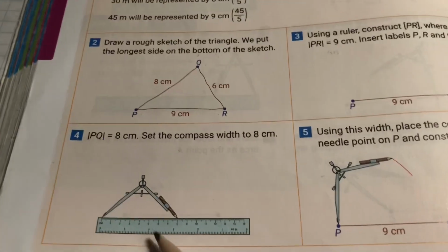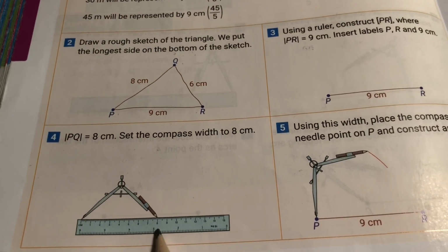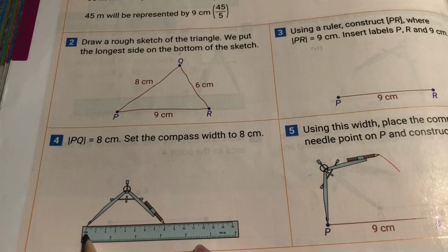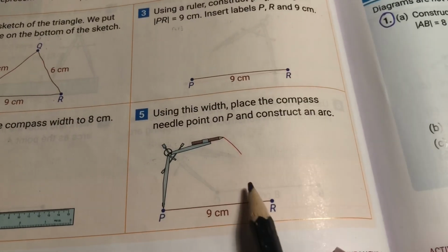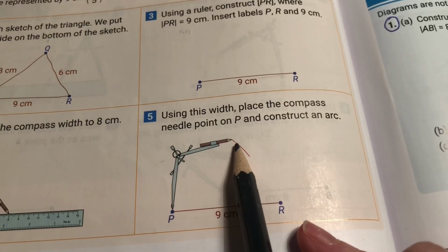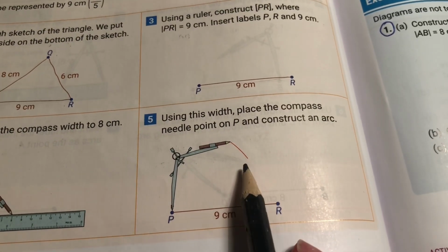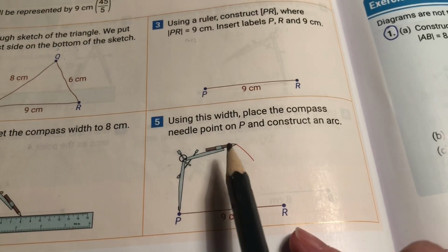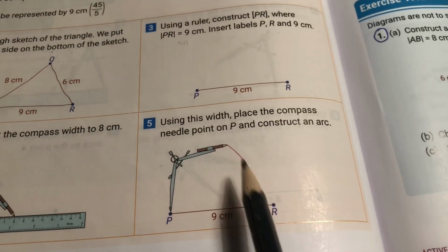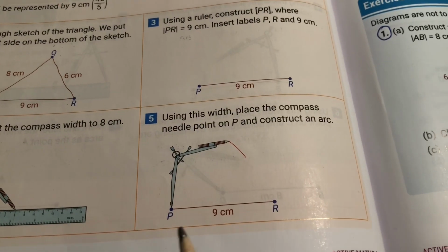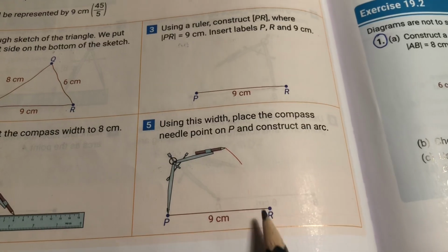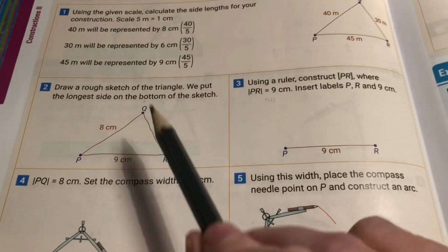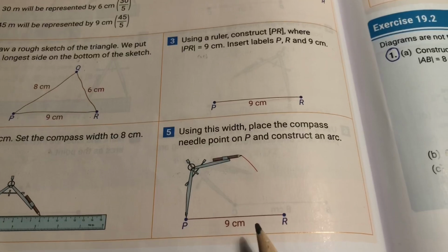So we'll first of all start off by opening our compass width to make the needle of the point on 0, the pencil point exactly on 8, put the point on P, sweeping around. Now sometimes people make a mistake, they just don't sweep quite far enough. We want to make sure they definitely cross, so don't be afraid of going right up and right down. That's absolutely okay. Remember, the construction lines are what the examiner is looking for, but you definitely don't need to go underneath this line. And as we know, it's going to be above it from our sketch.